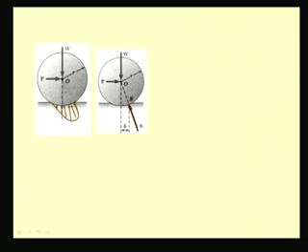Now, the moment due to this force, the vertical component of this force R is balanced by W, but the horizontal component of this R is balanced by this applied force P, which keeps this wheel in rolling motion, and the moment of this force balances this moment of this reaction.